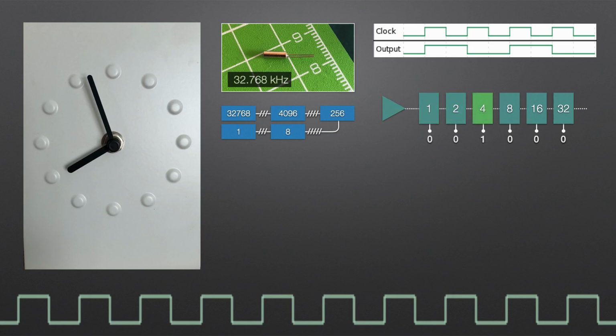Likewise, if you look at this diagram another way, the 1 slot is changing half as fast as the clock, and the 2 slot is changing a quarter. It's dividing the clock by 2 in stages. As you might imagine, there's chips available that hold all this functionality in a single package, and all we'd do is use these to take us right down to the slowest frequency we might want to use, which, let's say, could be half a hertz.